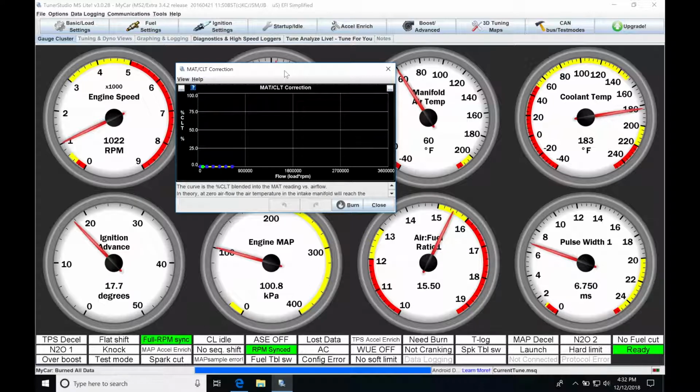But once we get moving, and once we start to have more air rushing into the engine, we get out of the zero airflow condition. In those conditions we're going to be reading more toward the actual air density coming into the engine, because we have a lot of air rushing over that air temp sensor. It's going to be a lot more accurate. And if you ever looked at a data log when driving in heat soak, and you start to drive for 5-10 minutes and you have enough air coming over the car and you're sucking air into the engine, you're going to see your air temperature start to drop if your air temp sensor is mounted into your intake manifold. And that's significant because then you're going to have a more accurate representation of your air density.